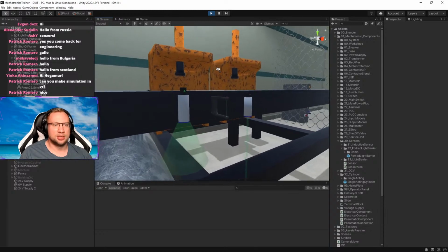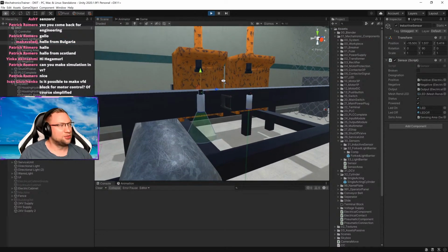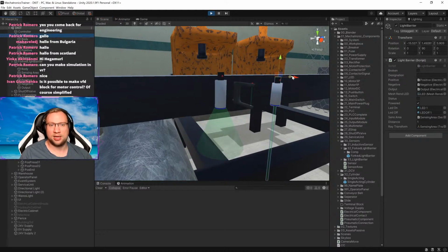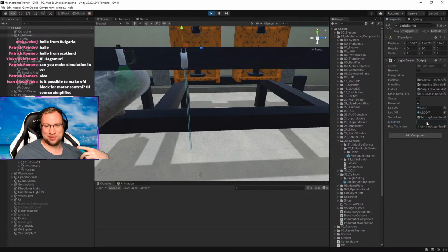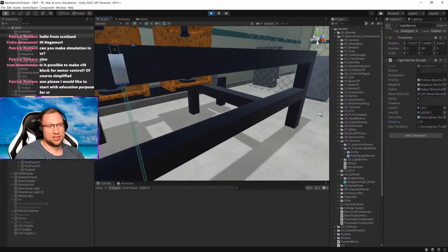So I've got these sensors now. For example, this one here, just an inductive sensor, and you see the green LED turns on and off. This one is also a digital sensor, a Boolean sensor, just on off. It detects something in the range. And for this one, and it's going to be in the end product, not just the programmer, me, can change, but everyone. For this one, you can change the distance, so you can adapt which range it is going to measure. Now it's going to measure the ground, for example. Hard to see, I know it's very small.